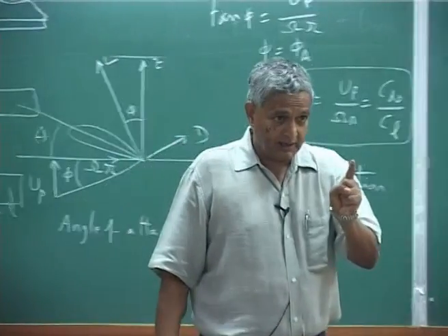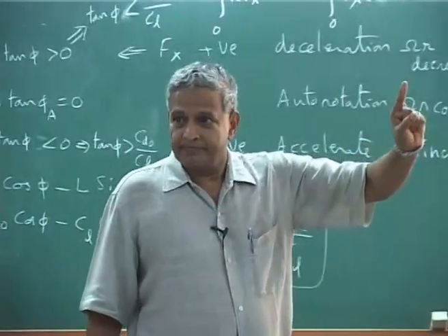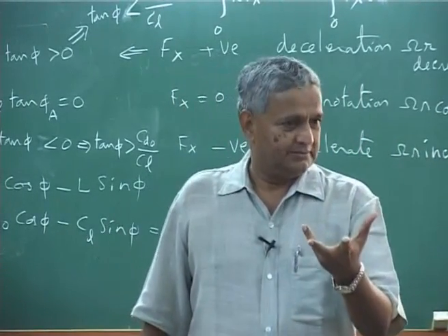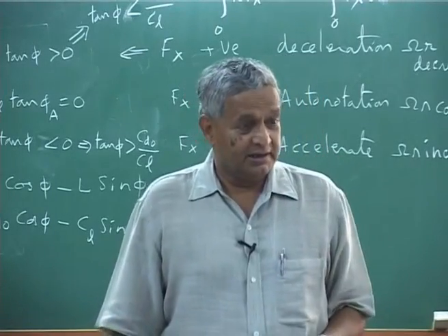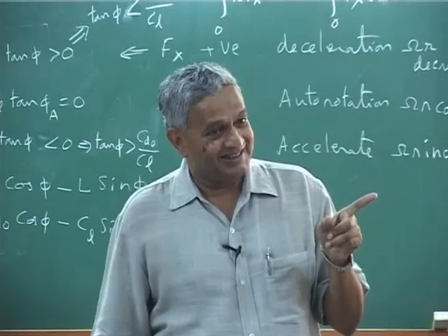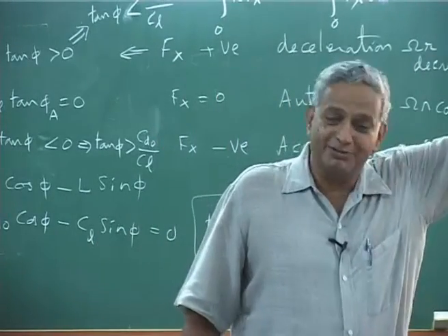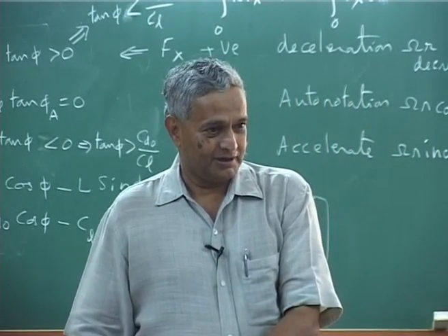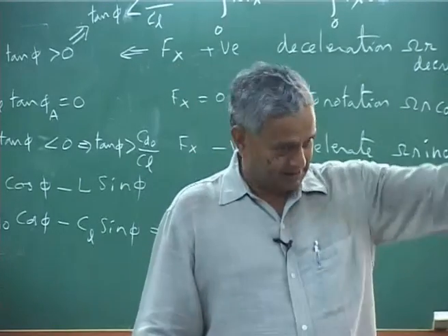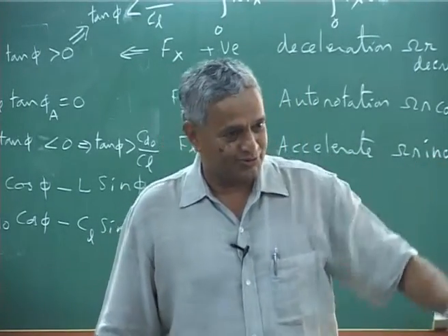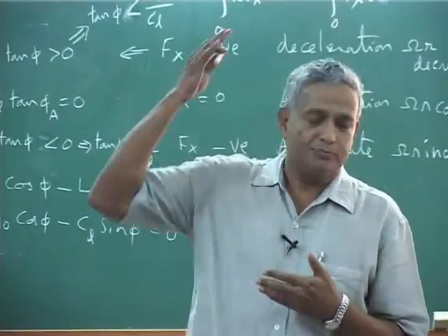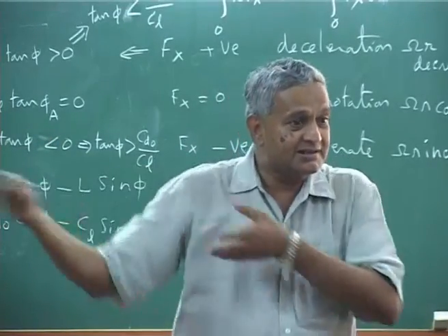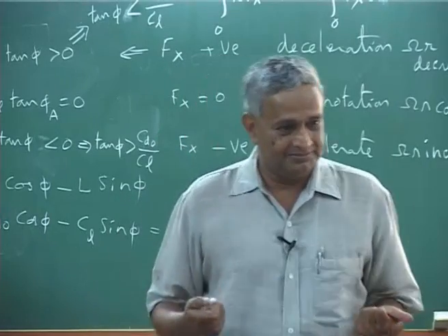Whether your maximum omega is what you have designed, because please understand, you rotate the rotor at a particular omega, because that is a fixed omega. Are you going to achieve that omega, or some other omega which is higher than the design value? Or is it going to be less than the design value? Because these are other issues. If your omega increases more, then your centrifugal load, everything, the root will get tremendously structurally strained.